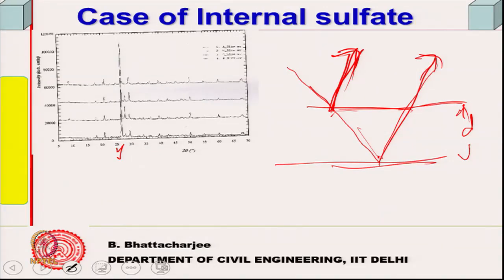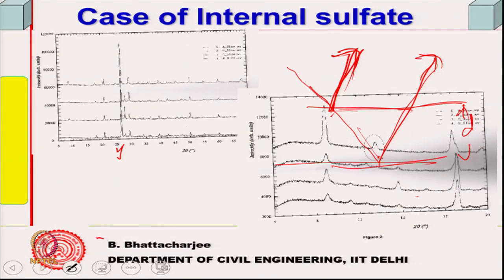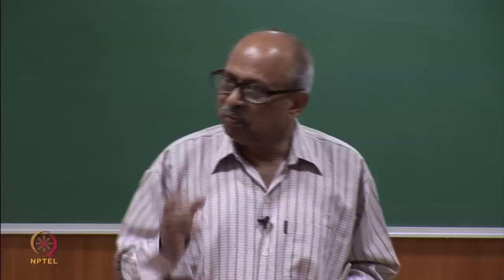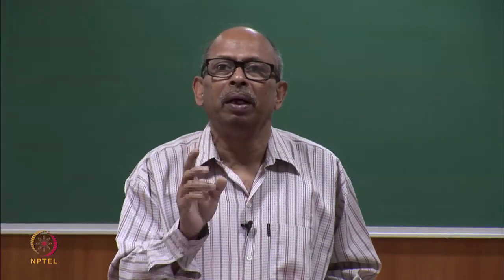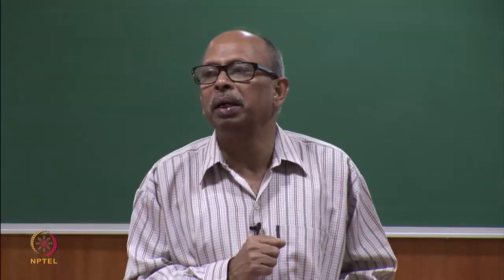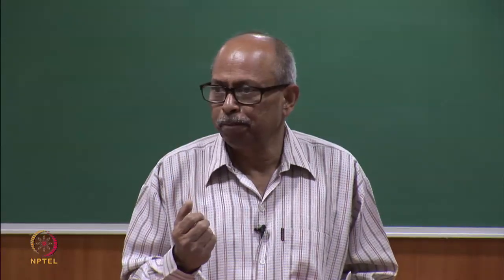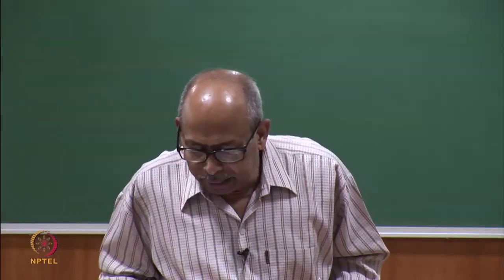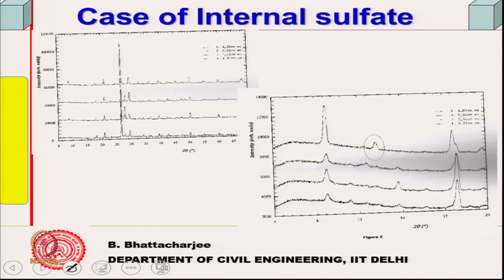So, we compared with the normal hardened concrete, where no problem would be there, but in this particular concrete, what we found was there are patterns of ettringite possible, which means there is a sulphate attack. So, confirming sulphate attack, first thing is of course the visual observation will show cracks of the kind that I showed earlier. You will find white crystals, and you want to further confirm, you can do some analytical testing like this. So, this is how we do it.